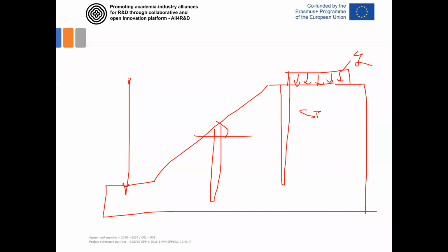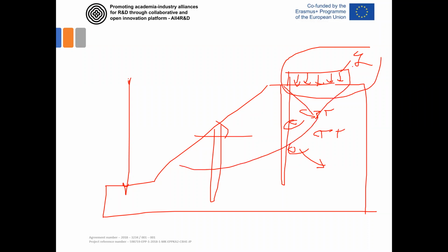It can be SPT data, it can be CPT data, it can be some soil sample data, like some test results here, and I'll send you all these results and ask you to predict the bearing capacity under this surcharge load. What's the bearing capacity of this soil profile with these in situ characteristics and with this geometry?